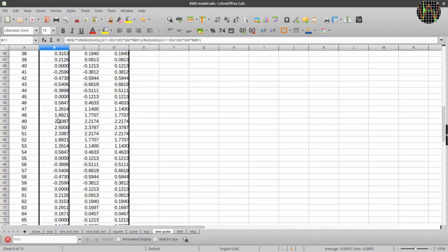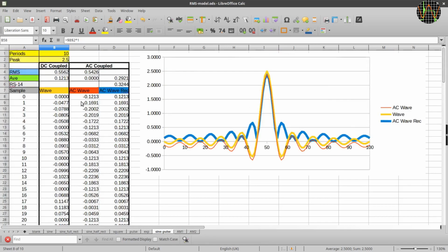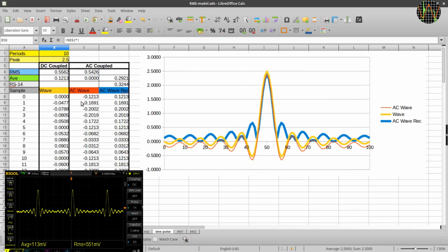A consequence of the math, there's a division by 0, which now happens at sample 50. By definition, for this function, the value at this point is 1, so rather than making it even more complex with ifs to catch this, I simply overrode the function at this point. As a consequence, you can't change the number of periods anymore, but in any case you shouldn't, because you would no longer get values you could compare with the measured data from the function generator.